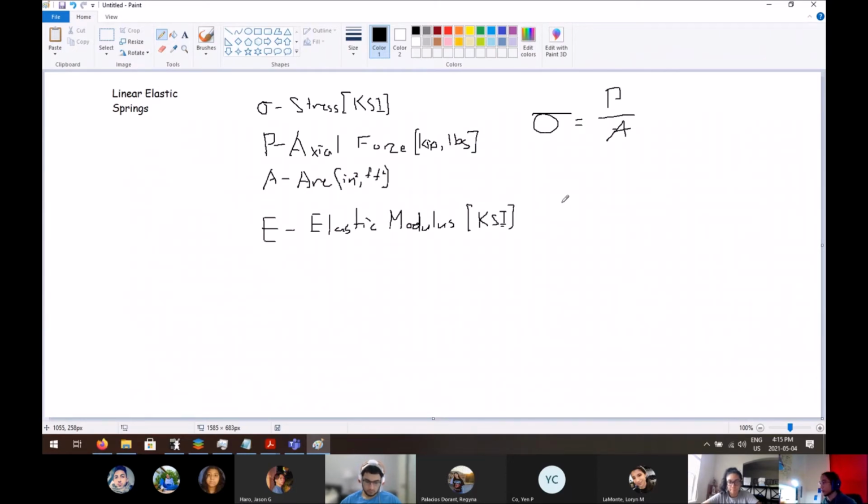That's sort of like the strength of a material almost. It's an innate property of a material that you're given. Steel has an elastic modulus of 29,000 ksi. Wood has like 1.5 thousand ksi or something. So it just sort of determines the strength essentially of a material, right?